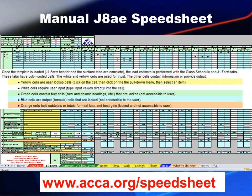One thing you need to know right away is the color codes on this sheet. Yellow cells are user lookup cells. Click on the cell and then click on the pull-down menu, then select an item. White cells require user input. Type input values directly into the cell. Green cells contain text cells, row and column headings, etc. They're locked and not accessible to the user. Blue cells are output formula cells, and they're locked and not accessible to the user. Orange cells hold subtotals or totals for heat loss and heat gain, and they're locked and not accessible to the user. Therefore, you've got to put everything in right when you're doing the yellow and the white cells, because the other ones are not accessible, so you can't really force them to do what you want.